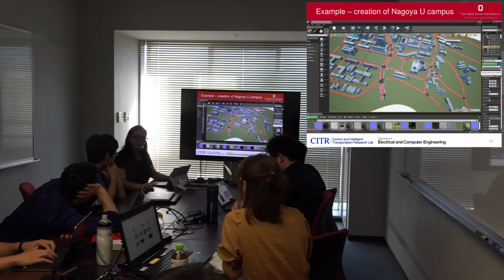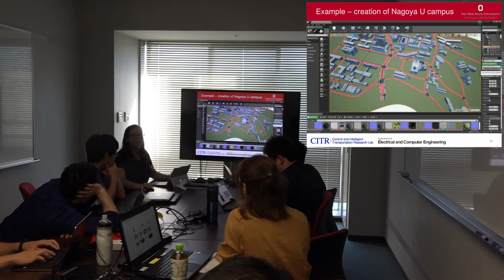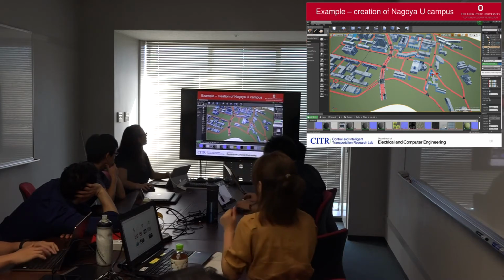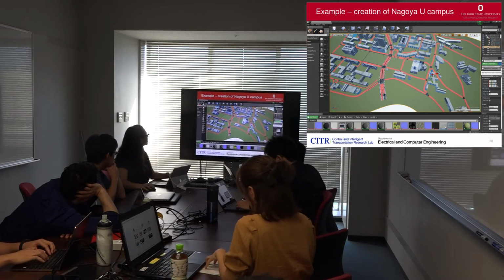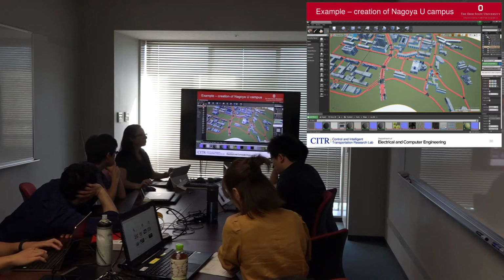Even without RoadRunner, the original Unreal Engine can also generate these, right? I mean, you have to do it almost manually. You can. Here in the modes tab of Unreal Engine, it says search classes. You look for the OpenDrive actor and the spawner actor.